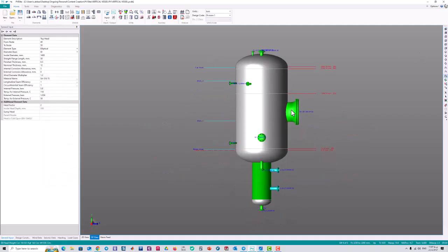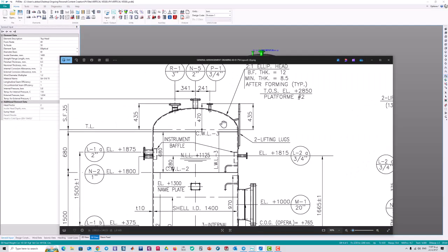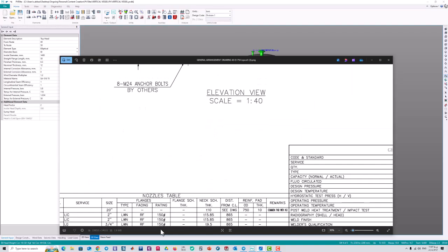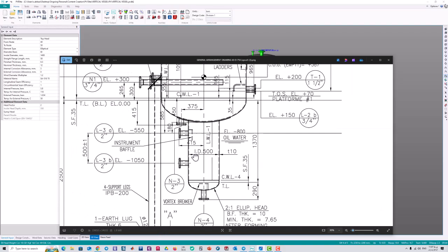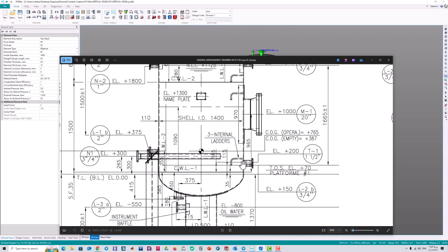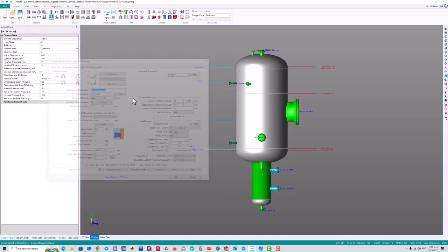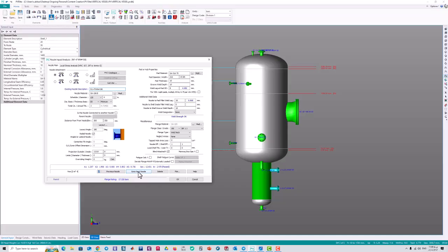The last nozzle is T1. It's only shell 1. Select shell 1 and click on nozzle input. Click till we reach the add new nozzle, to avoid duplicating the nozzle over the previous nozzles.